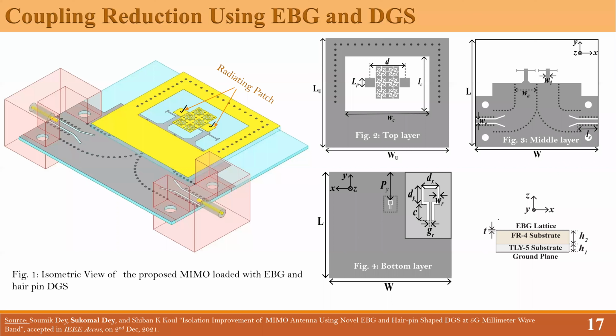Now after that we developed these antennas. This is the fabricated image of these antennas. Then we checked the performance of each individual part of these antennas, and then this is the overall antenna. You can see the photographs of it, and we have compared it with a 5 rupee coin just to show you the size of this antenna is very, very small. The most important thing here is that you can see the isolation is around 71.9 dB, close to 72 dB of improvement, at close to 28 gigahertz.